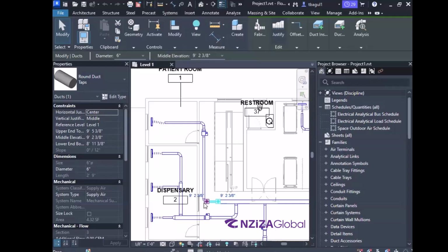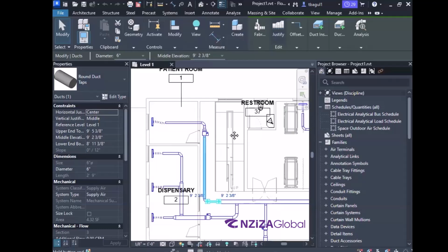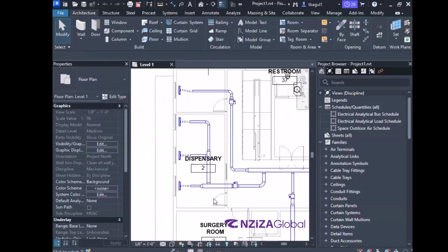All right. So going back to the chart now. The reason I was talking about the heat load calculation and everything, now all of those minimum total air changes per hour, you'll need to start counting them, and then accordingly we will size our duct, right? So now talking from the last point, over here we just have 85 CFM, correct?